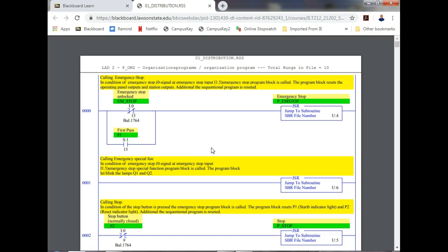Okay. The other thing we have is an emergency stop, which is input 13. But remember, Allen Bradley PLCs go in words, right? And what's a word? 16-bit. Siemens PLCs go in bytes. So what's a byte? 8 bits. So the addresses, or the module numbers, go in bytes. So we're going to have to figure out how to go from a 13 over to something that's on our PLC, right? That makes sense.